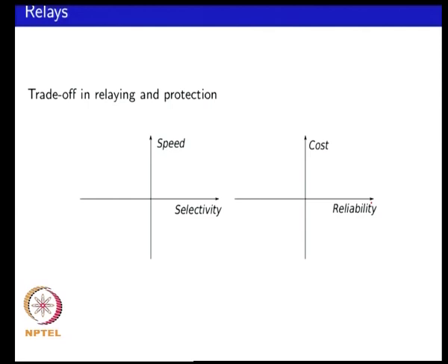You should also not trip for under voltage when you are having an overcurrent. So, it should be tripping for the right reason. It has to be selective in making the decision of whether to trip or not, and typically when you want decisions at high speed, you might be more prone to noise, and more prone to making the wrong decision.